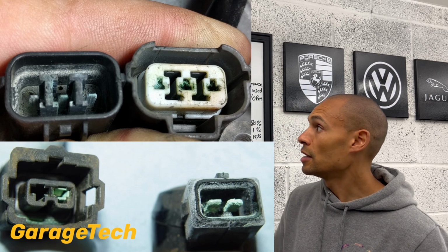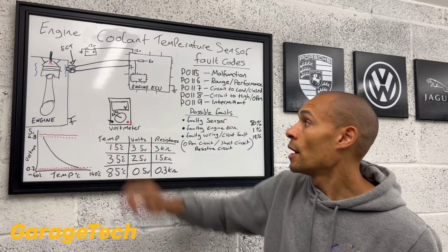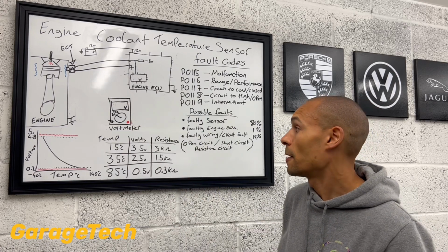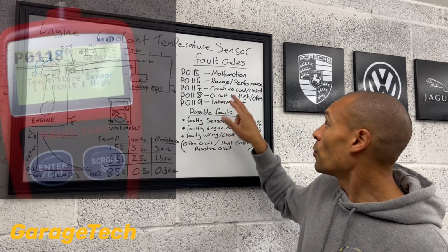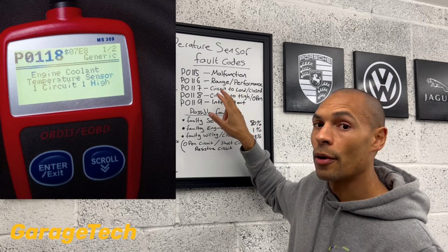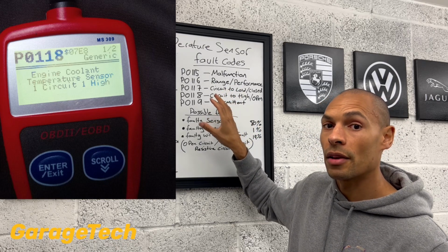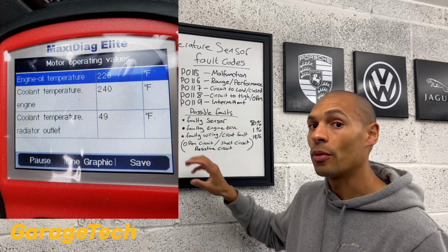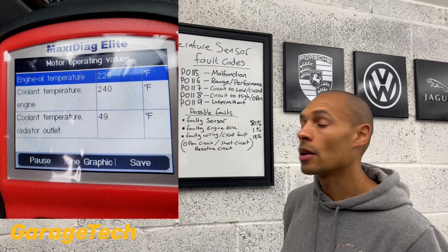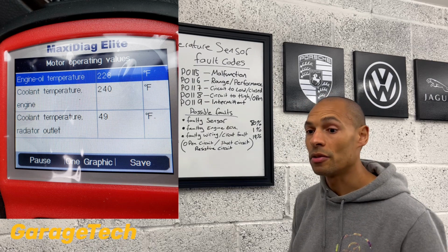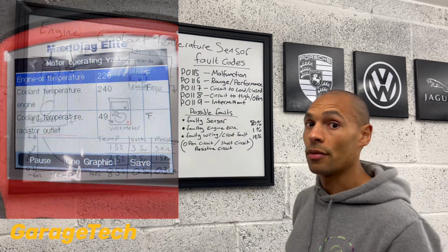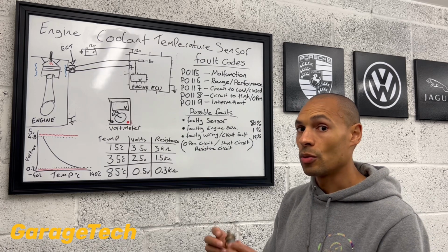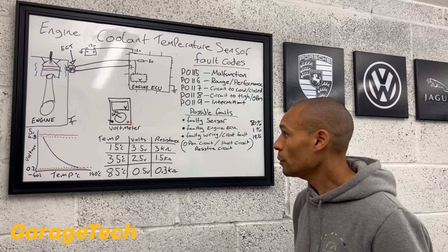That's some of the initial checks you're going to want to do straight away before you start actually taking the sensor out and bits and pieces like that. As I said, if you've got a fault code reader, that's really going to help, particularly if you can measure some of the measured values or the data blocks with it, because that will also help aid you in your diagnosis. Now, if you haven't got some of those things, hopefully some of the tips I'll talk about will help you get through deciding whether it is an actual coolant temperature sensor fault or not.